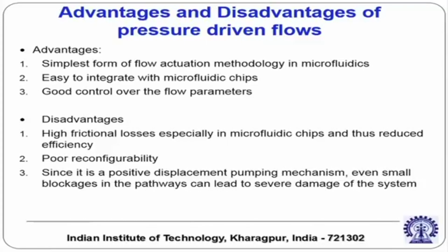So the advantages, why we have started with the pressure driven flow in microfluidics is because it gives one of the simplest forms of flow actuation methodology in microfluidics. It is easy to integrate with microfluidic chips. You basically require some very simple driving mechanisms like the syringe pump for example. So we will have one experimental demonstration soon as a part of this course where we will demonstrate how you actuate a pressure driven flow and how you calculate friction factor and all these experimentally. It is easy to integrate with microfluidic chips, and it is possible to have a good control over the flow parameters. So that is advantageous, but there are disadvantages, or sometimes disadvantages is too strong a word, we may better say limitations.